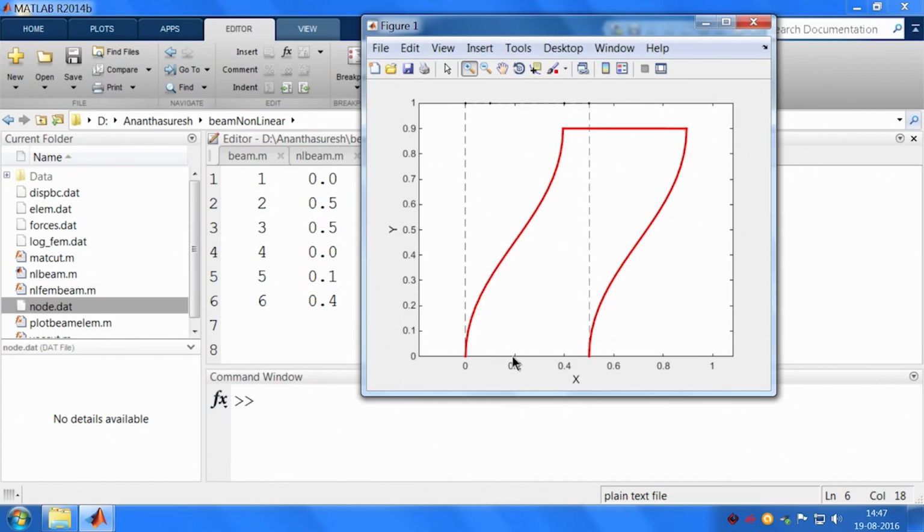So the center I will have, that becomes a stage now, that becomes our moving stage, which is supposed to have purely x motion and no y motion, because we see that this top stage cannot have purely x motion, it has y motion, right. So if we do this, just as this is moving down relative to this line, the next stage that we hang, that is going to move up closer to its relative frame. So this downward motion, this upward motion, both are supposed to cancel. So you get this stage to move purely in the x direction. That was the intent of the folded beam suspension.